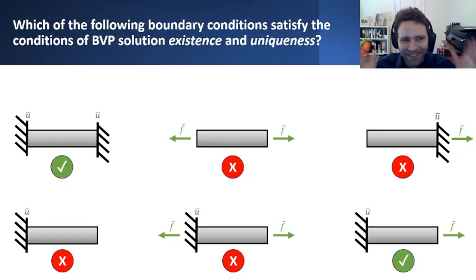You might think, isn't this over-constraining the member? Am I not imposing too many constraints? Well, there's nothing to say that I can't prescribe what the displacement is, even everywhere along the length. Certainly that makes solving these boundary value problems much easier, because I'm basically telling you what the solution is.